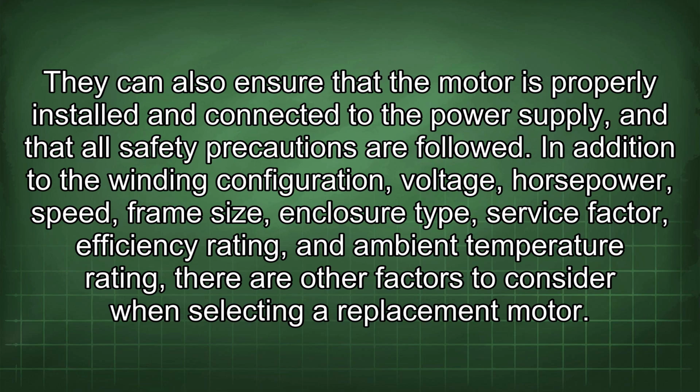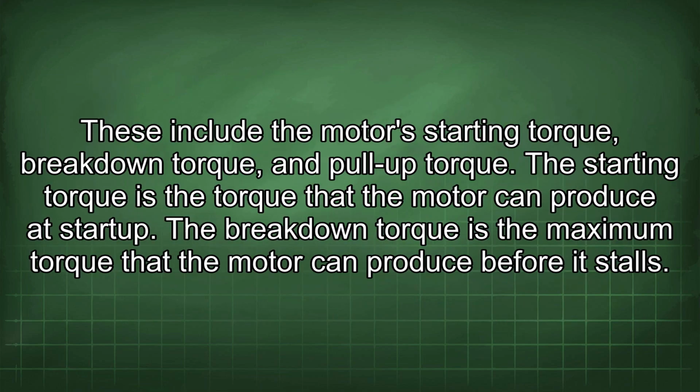precautions are followed. In addition to the winding configuration, voltage, horsepower, speed, frame size, enclosure type, service factor, efficiency rating, and ambient temperature rating, there are other factors to consider when selecting a replacement motor. These include the motor's starting torque, breakdown torque, and pull-up torque.